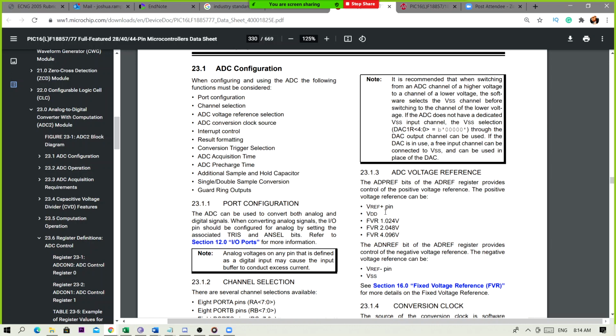So for the joystick or the linear pots, you'll need to use 2 channels, but it's resistive. So that's straightforward. The moisture sensor actually generates a voltage. So you're just connecting it, but then you have to figure out how you're going to convert it, because it's not like you could control the voltage. You have to adjust your specifications to match the voltage on the sensor. And if it's the photoresistors, again, you'll need 2 channels because you have 2 photoresistors.